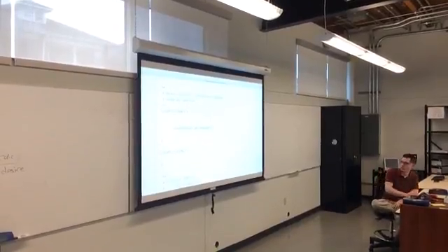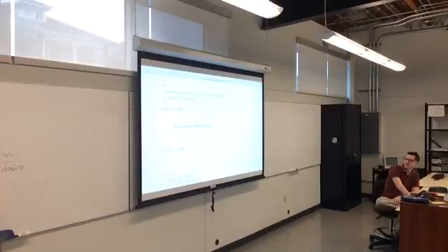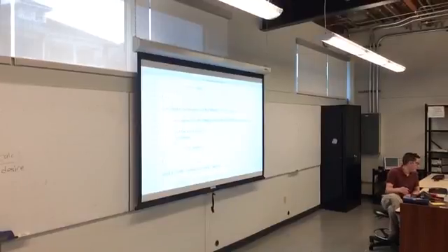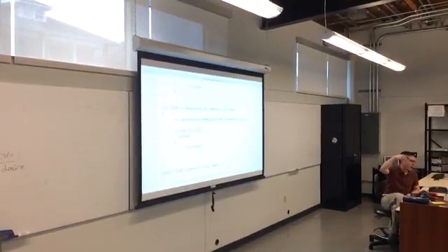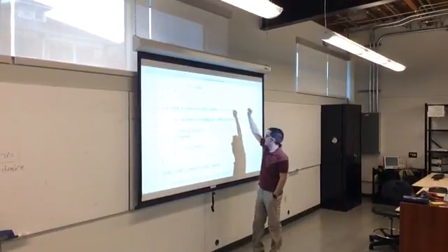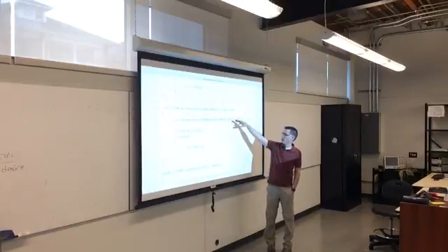The only thing that I changed in code from my SPI version to this version is how write register was implemented. Previously, I would change the chip select line. I would then do SPI transfer. I deleted all that and just now call write register. So where your old class would try to write to an internal register and write a value, here you've got to write to its I2C address, and then its value. So you've got to figure out what the I2C address is. And I'm looking at the code now, and I may have left the I2C address hidden in the code. That's fine if you can find it.